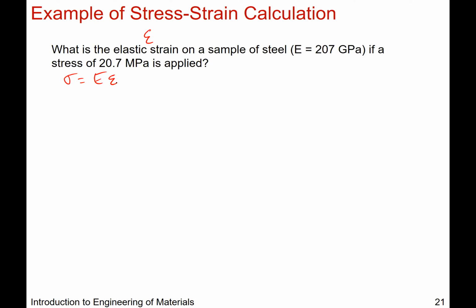So if we're asked to calculate the strain, then we know that it's just stress applied divided by the elastic modulus, which is 207,000 megapascal. So I just converted gigapascals to megapascal because strain is unitless, right? So be sure to convert your units.